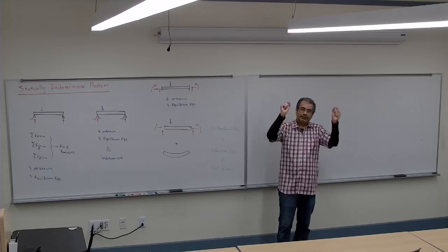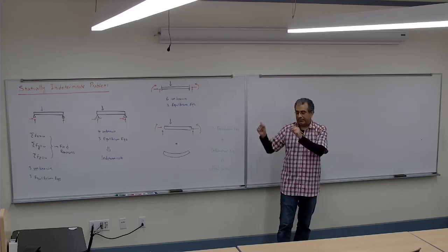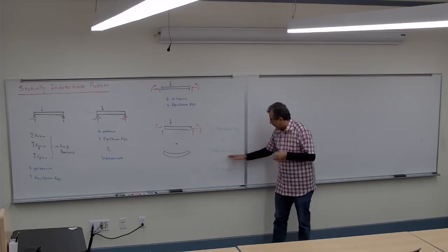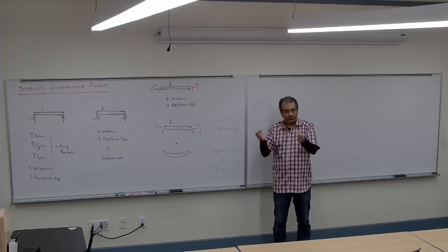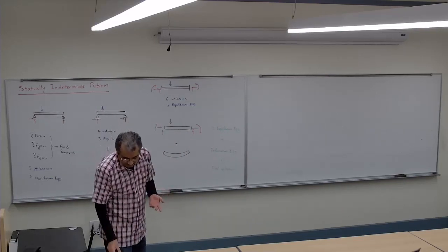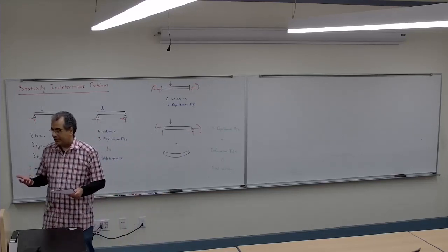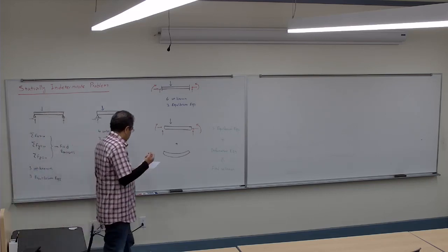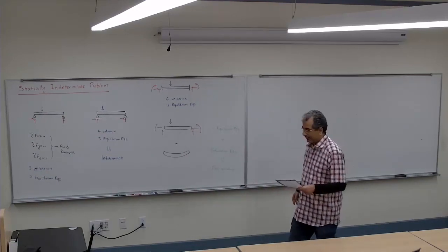So you bring out every single element and write the equilibrium equation for every single element, and then still you are going to need more equations, and whatever is left, you're going to see how that beam deforms, or how that column deforms, and then use the equation from deformation to solve. Here, usually we are dealing with a very simple problem, but the concept is more important: how we are going to use the deformation equation to solve it. Any question up to here? It's going to make more sense when we look at the examples.